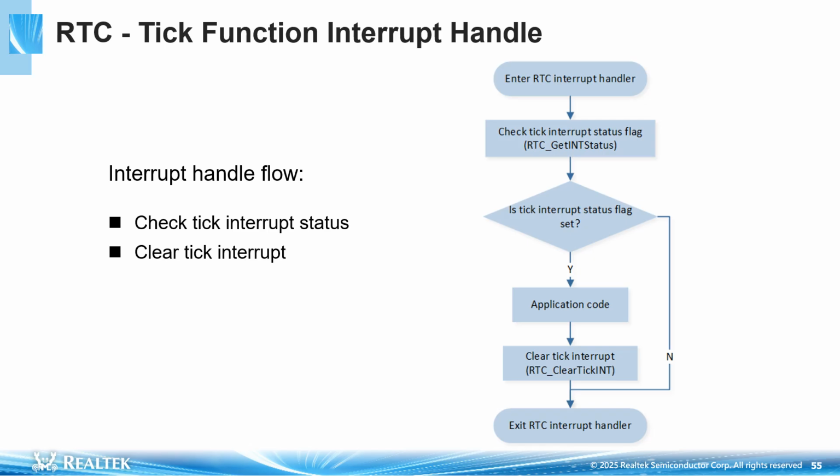When the counter counts once, it will trigger the tick interrupt. In the interrupt function, the interrupt status flag needs to be checked first. If the tick interrupt flag is set, the tick interrupt status of RTC needs to be cleared.